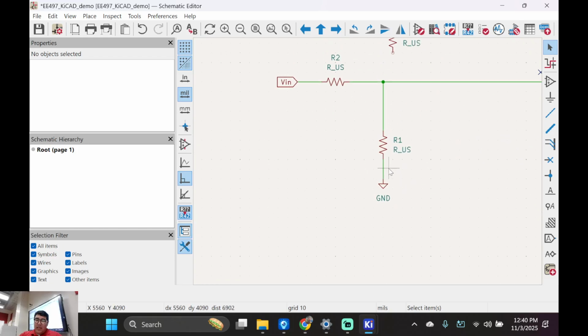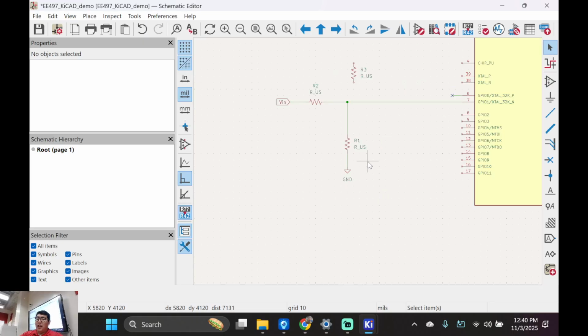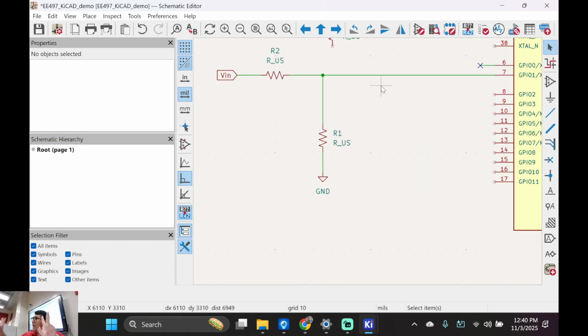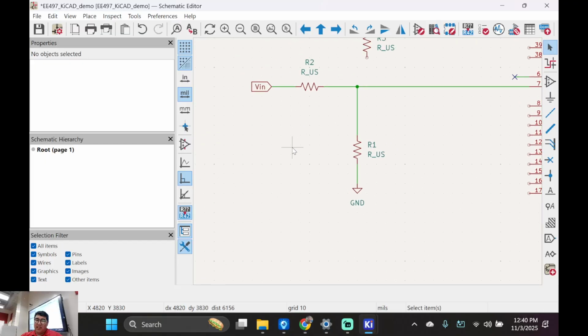And then there's another error you might witness when you're doing your schematic design, which is that you need to power your actual schematic using power flags. So this right here is an input, that's something that I don't know what's going to be. Ground is a source of power because it's a reference. To add a power flag, not that one. Let me see, is this a power flag? No, I'll just show you.